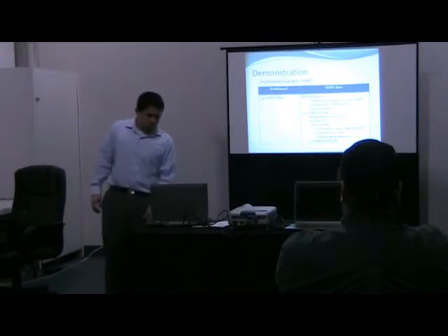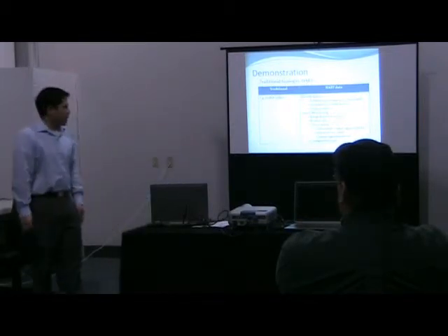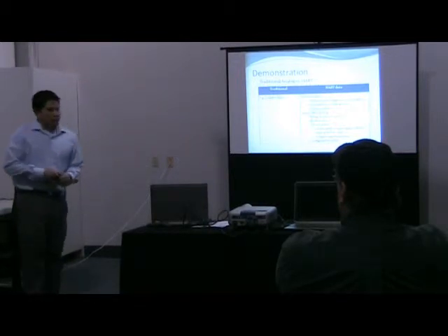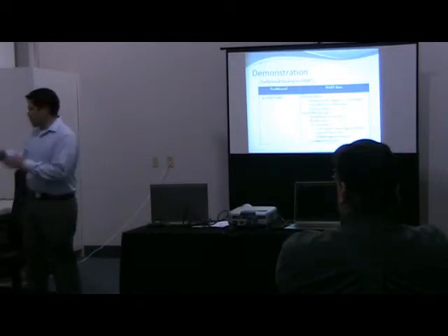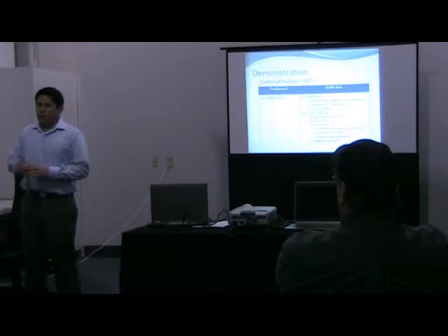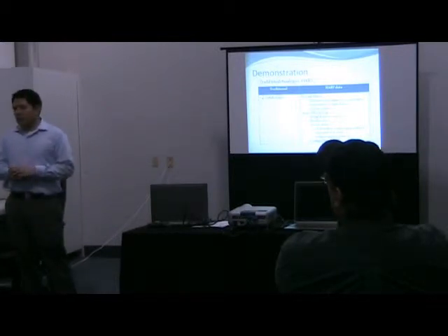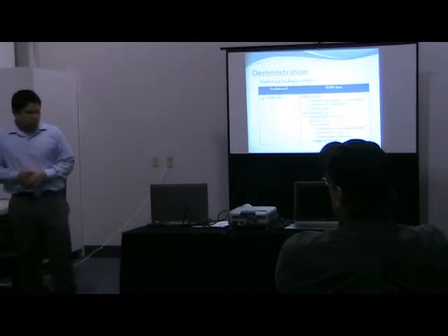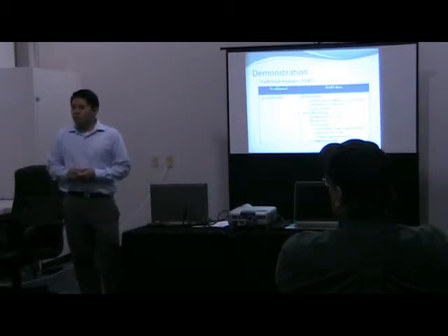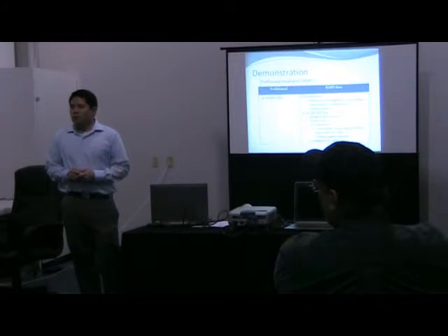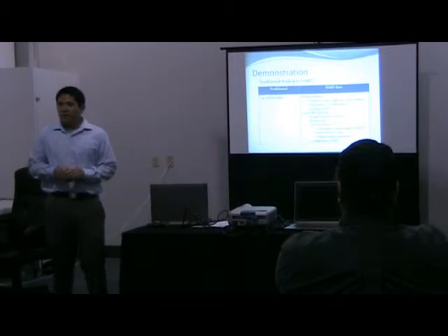What does that mean? Configuration valid is a comparison between the PLC limits and what is currently configured on the device. If somebody punches in a value outside of those limits, the system will warn of it. Or can they change the scaling at the instrument, for example? Yeah. Would it be, if you set it for 15 pounds, 4 to 20 milliamps, and you're overranged, it says, wait a minute, before you do this, you might not want to do this? Yes. That's exactly what that warning is for.